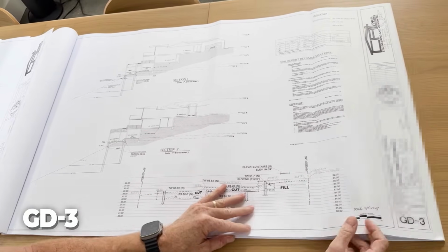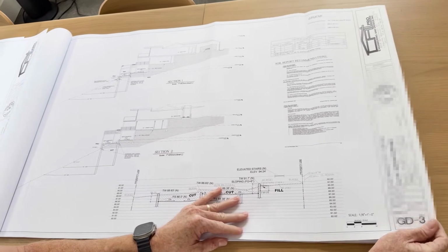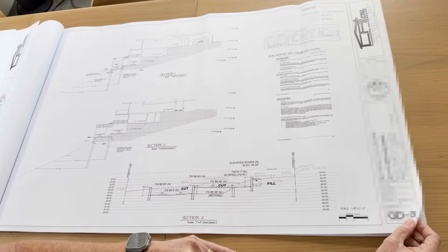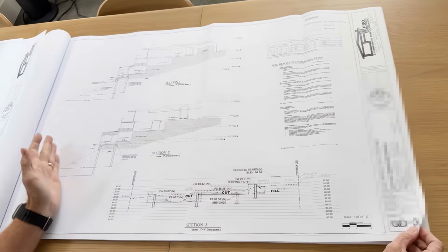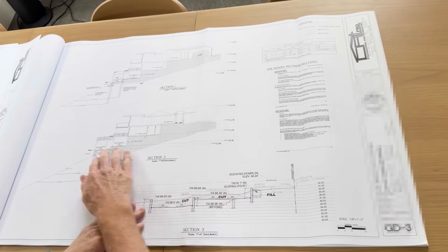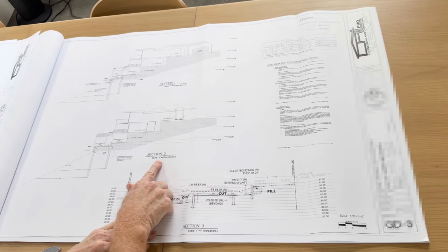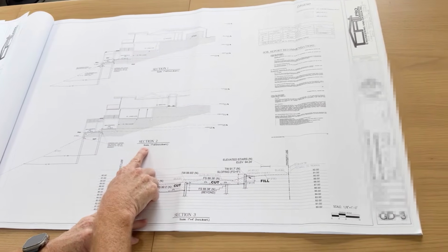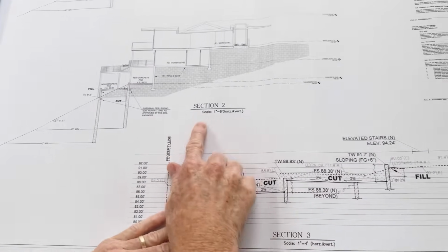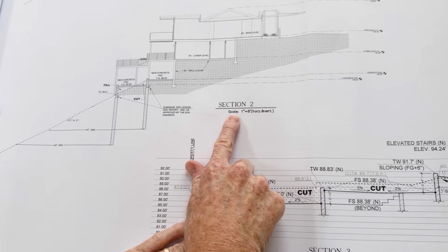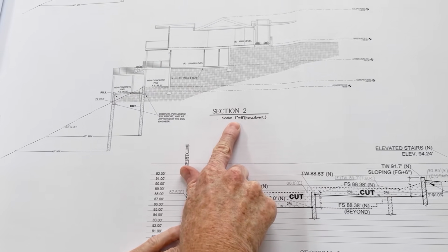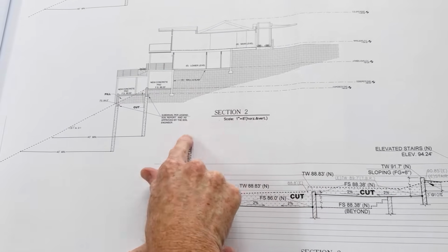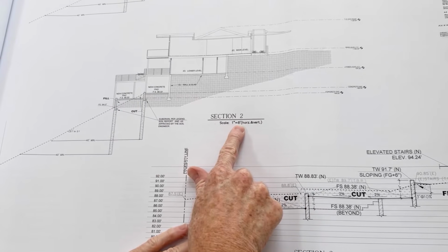I don't want to get too concerned about grading because like I said, we could do a whole segment just on grading as we could with structural, but just for example purposes, again, cross sections. The important thing that we want to pay attention to here is anytime you have a situation where it's a full set of drawings and you've got what the architect has recommended as a scale, he's basically saying that 1 inch on this page equals 8 feet, horizontal and vertical.